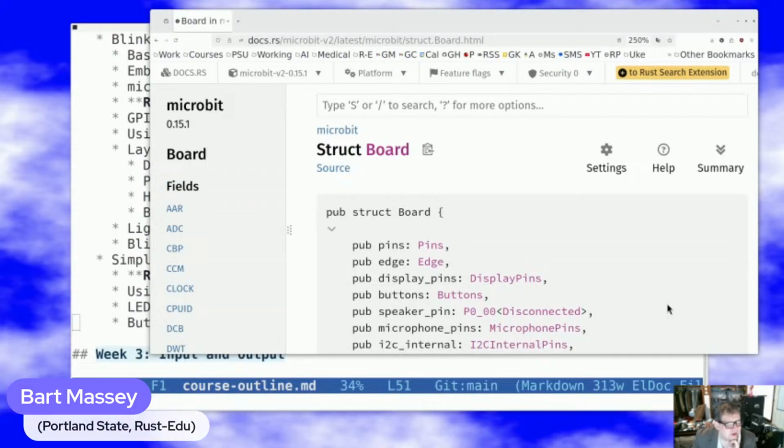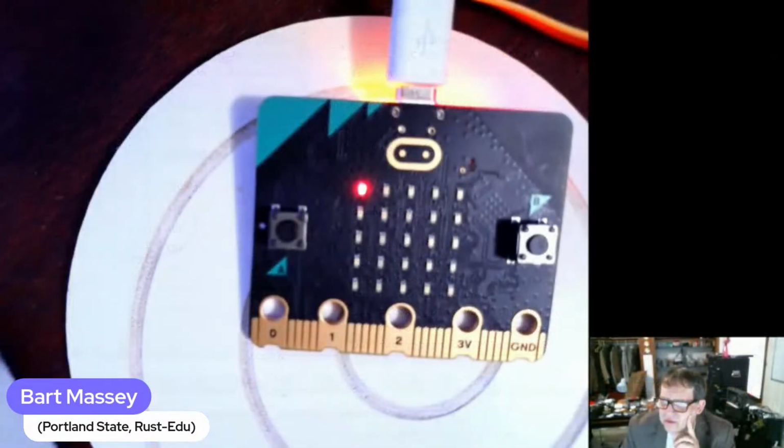So what I was going to say before I forget, though, is these buttons here on the microbit, the A and B buttons, they break off really, really super easy. They're not expensive to get a replacement for, except that you can only buy the replacement switches usually in reels. So then it does get expensive. So be careful with the buttons on your microbit. I actually put hot glue around the buttons on some of my microbits to keep them from breaking off. But I also bought a reel of replacement buttons.